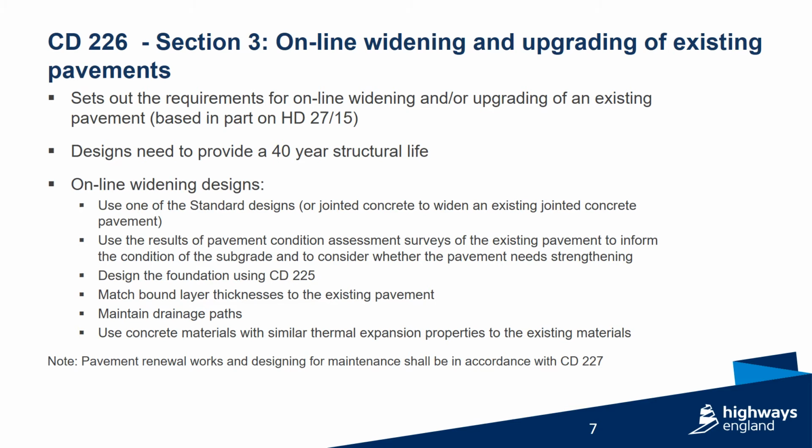Designs need to provide a 40-year structural life. Online widening designs shall use one of the standard designs or jointed concrete to widen an existing jointed concrete pavement, if applicable. Online widening designs shall use the results of pavement condition assessment surveys of the existing pavement to inform the condition of the subgrade and to consider whether the pavement needs strengthening, and if so, design the foundation using CD 225.